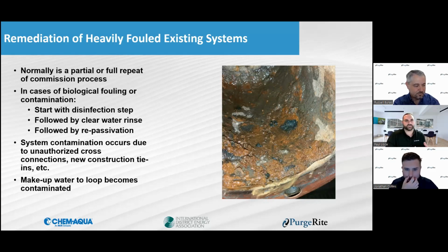So we can use some chemistries that can get added, coagulants, HEDP, to sequester that iron, pull it together, drop it out, make it bigger, so the filter can get it out of the system. It's really about working together and understanding that filtration is a great way, but if you can't actually filter it, then you're wasting your time. So from a chemistry standpoint, we can help Russ clean that system up quicker by getting the particulates to the right size in order to be filtered out.